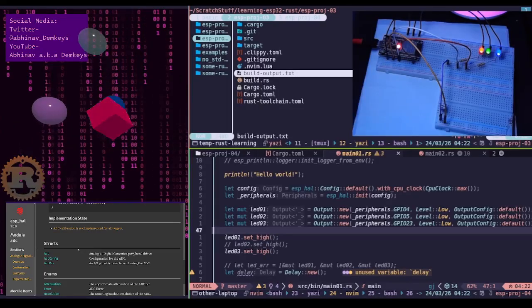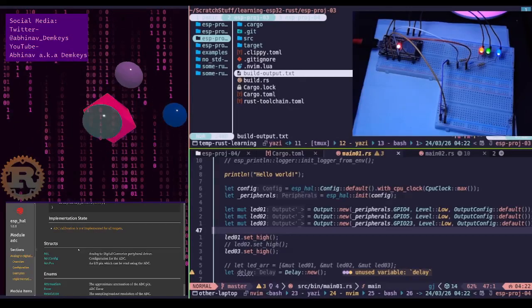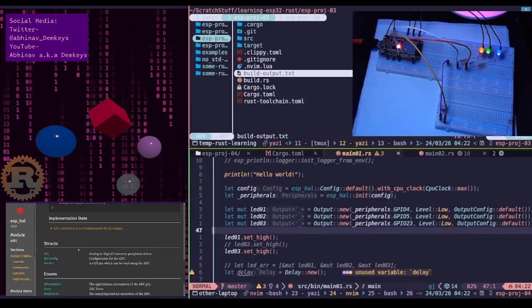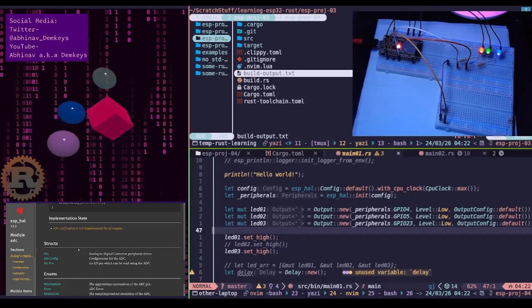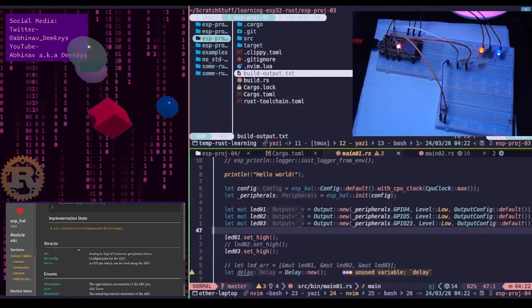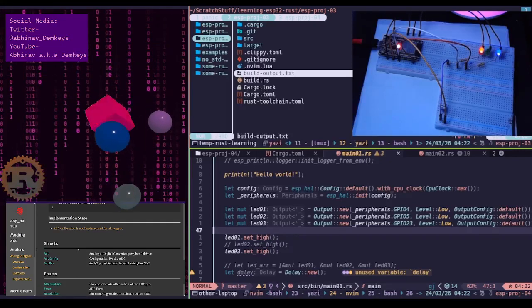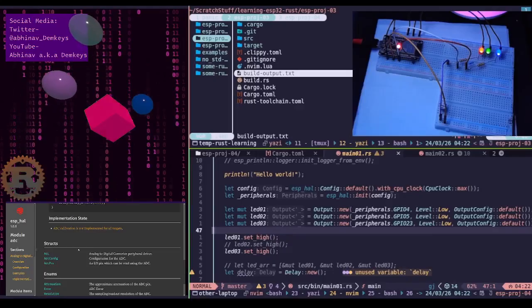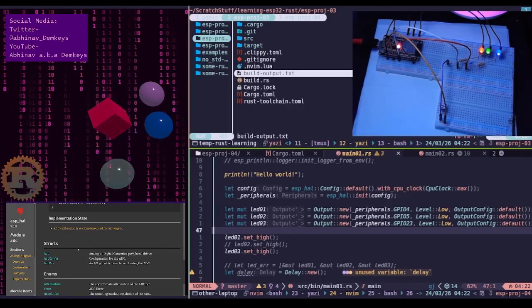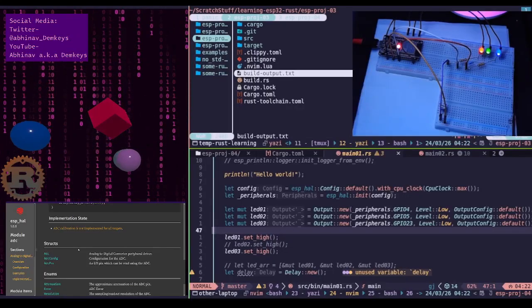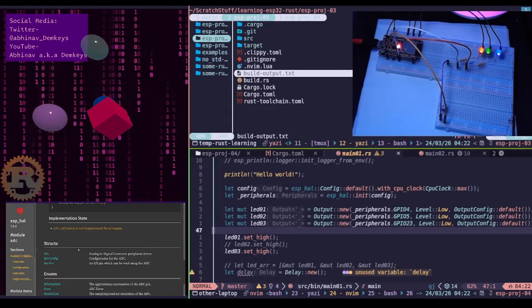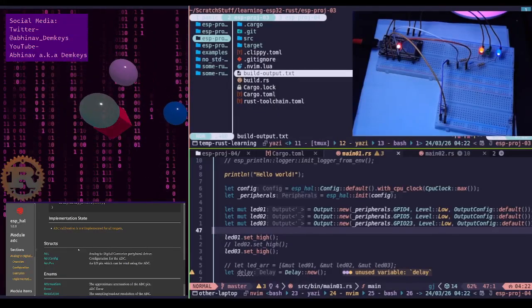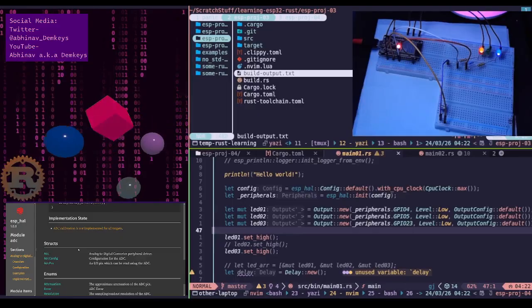Okay, all right. So you can do 12-bit. In most Rust ESP HAL implementations, you can set the bit width to 12-bit, 11-bit, 10-bit, and 9-bit. Okay, so that would be 4096, 2048, 1024, and 512 respectively.